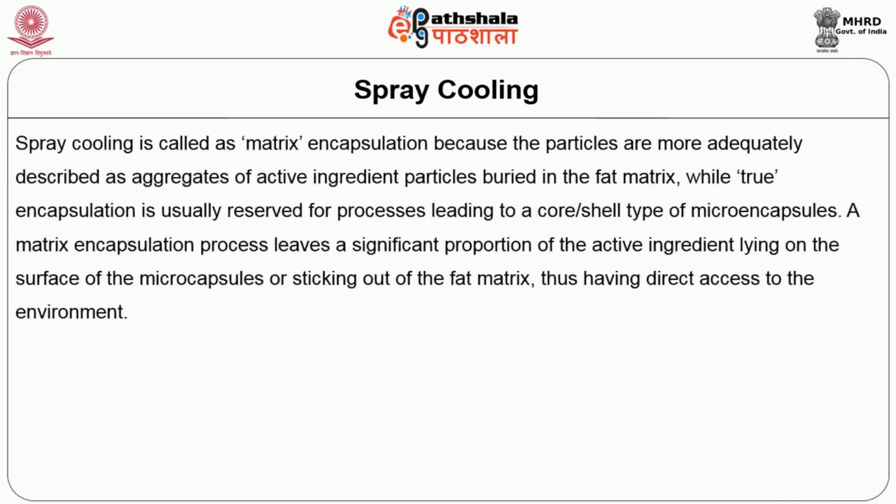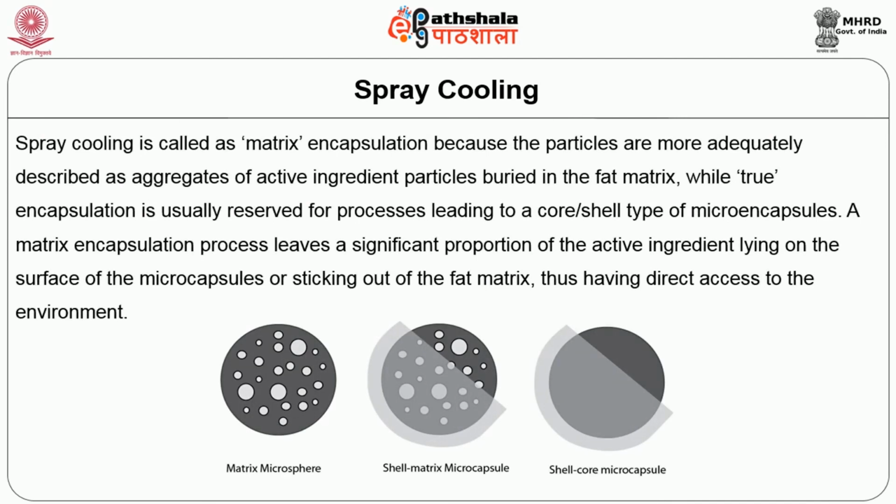Spray cooling is called matrix encapsulation because the particles are more adequately described as aggregates of active ingredient particles buried in the fat matrix, while true encapsulation is usually reserved for processes leading to a core shell type of microcapsules. A matrix encapsulation process leaves a significant proportion of the active ingredient lying on the surface of the microcapsules or sticking out of the fat matrix, thus having direct access to the environment.